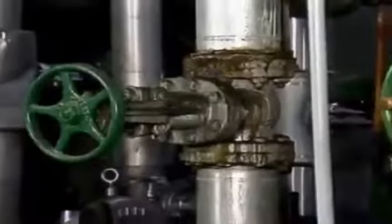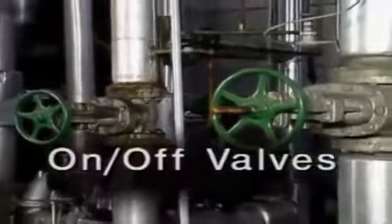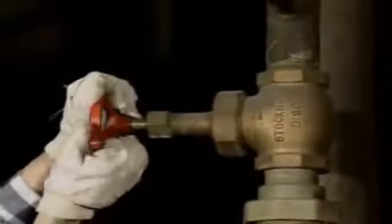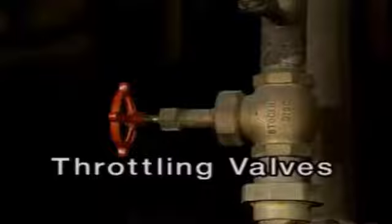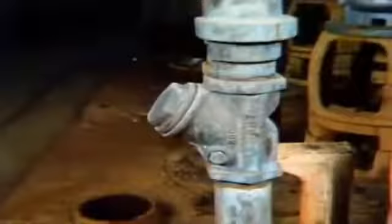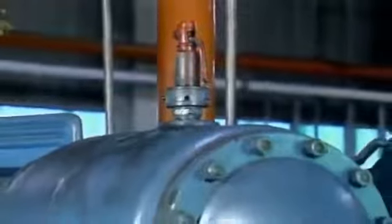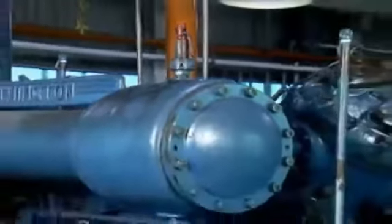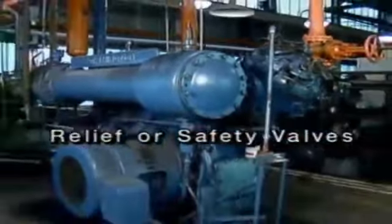Many valves operate in either the fully open or fully closed position. These kinds of valves may be referred to as on-off valves. Other valves regulate or throttle fluid flow. This can be done by partially opening or closing a valve. Valves that operate in this way are called throttling valves. Some valves may allow fluid flow in only one direction. These valves are called one-way valves or check valves. Still other valves are used to relieve excess pressure from a process system to protect equipment and personnel. These valves are called relief valves or safety valves.